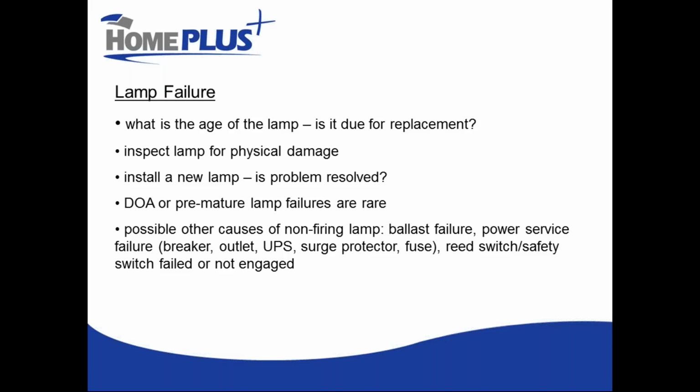Yeah, so that to me is suggestive that the retention time within his system is long. So he's very likely not having any problem meeting his CT requirements with the storage that he has.